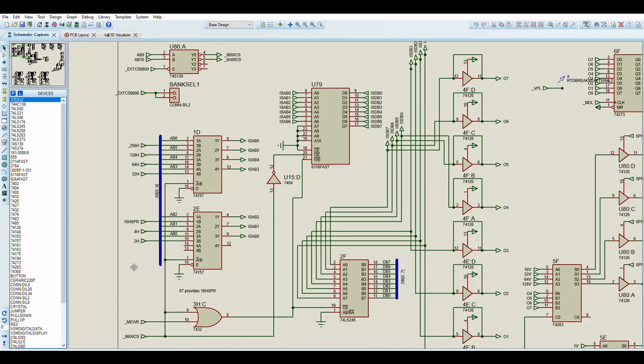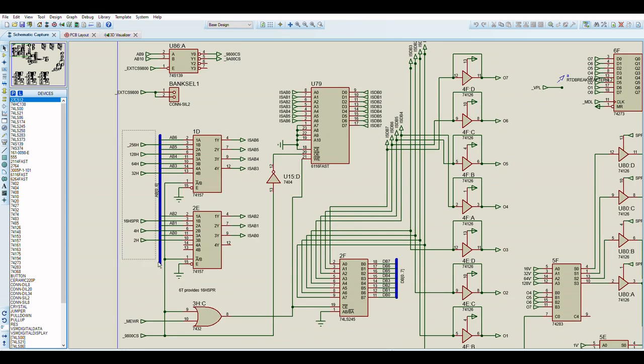So if you're addressing the external memory data bus, then it turns off the clocked horizontal pixel position, so it doesn't use that as the memory address. It uses the CPU's or the external memory bus address, and it feeds that through to the address bus on the RAM here. If, however, you are not writing anything from the external memory bus, then all of the memory addresses that it reads come from the horizontal pixel position on the screen.